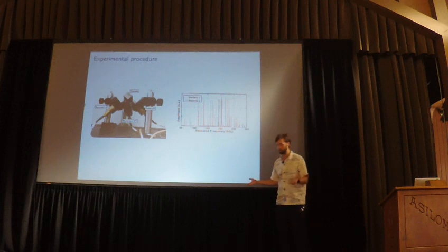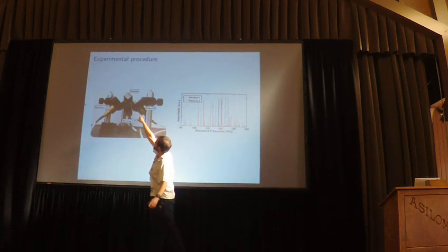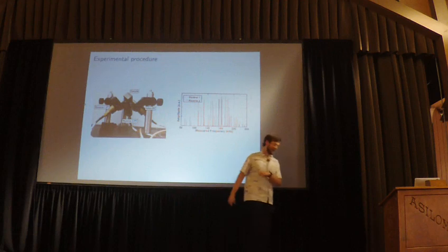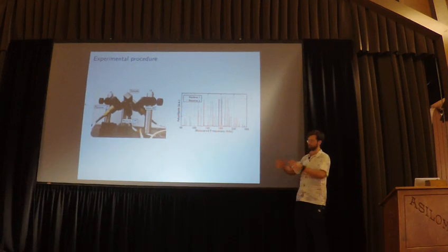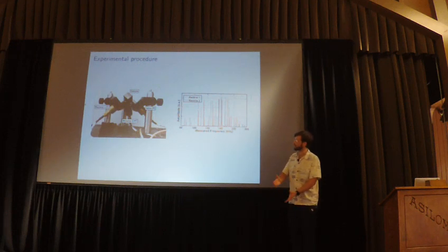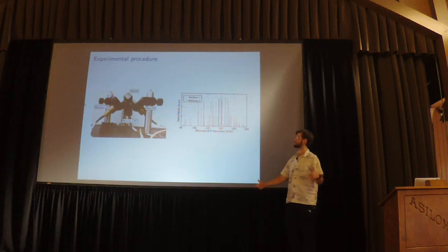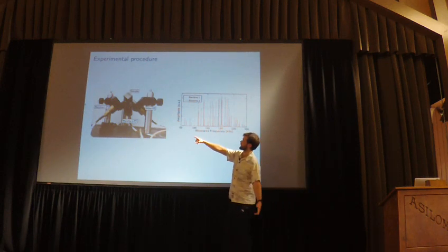And much in the same way that we can ring a gong, we can take a little lump of material, one of these superalloy materials, put it in some sort of ringing apparatus, and figure out where it likes to vibrate, like the frequencies, the noise that it makes. The key thing here is that where the sample resonates is going to be a function of its geometry, and of these elastic constants. We know the geometry, we want to figure out the elastic constants, and that's a typical experimental setup for this.